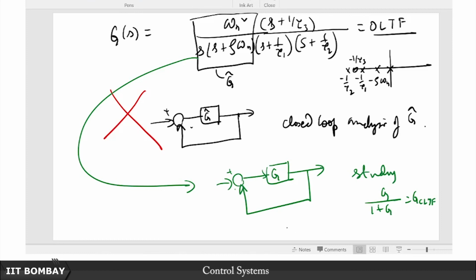Instead, you look for the 5 sigma rule or pole 0 cancellations in the closed loop transfer function. Very important point. Do not look for pole 0 cancellations in the open loop transfer function. Put it in the closed loop configuration. Find out the closed loop transfer function. In this case, of course, it's unity feedback, so we know it has a particular form.